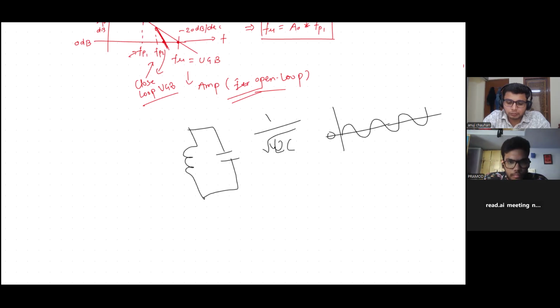Then the oscillations will occur, right? Normal, because no feed forward source is there here. If we take the voltage or current, whatever, it will go under oscillations. So I am asking why these oscillations are coming, what is the reason? Let's say this is a pure sine wave, and no energy is dissipating, because these are energy storage elements and no resistance is there. But how are these oscillations occurring? What is the main reason for oscillations?